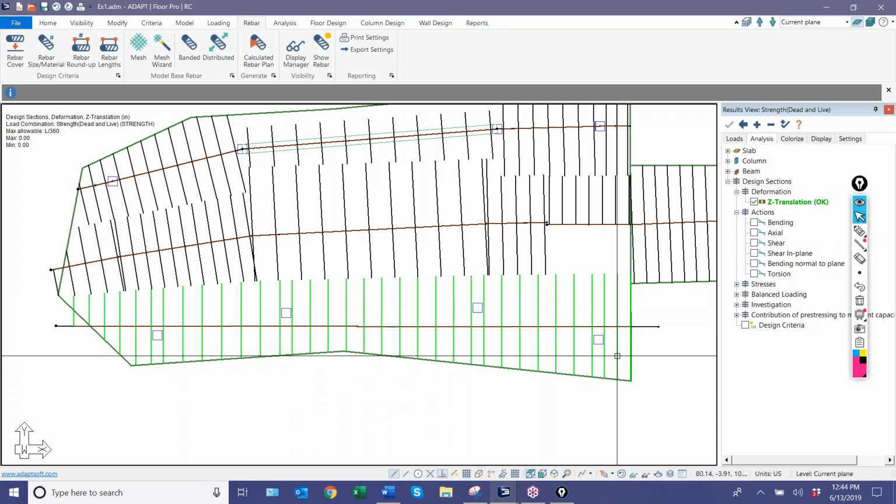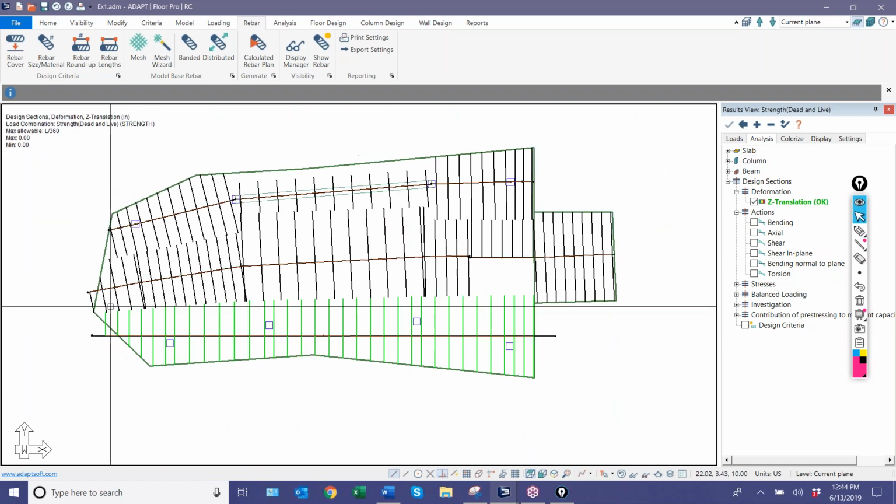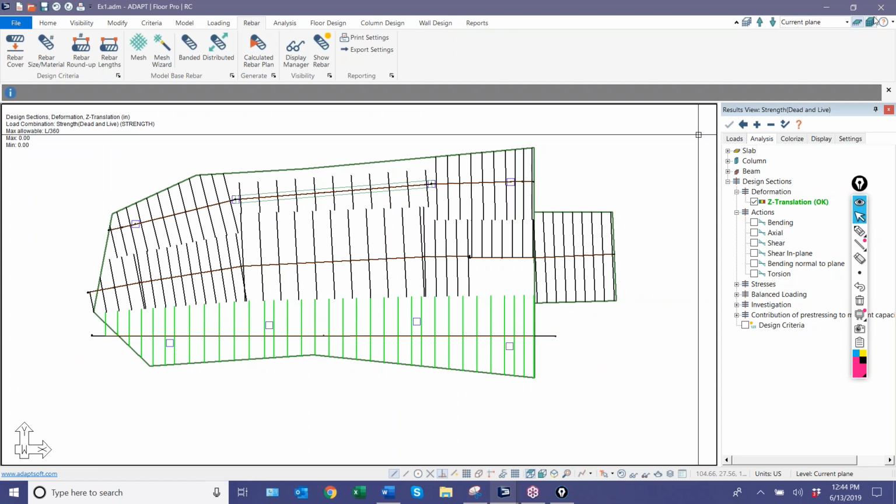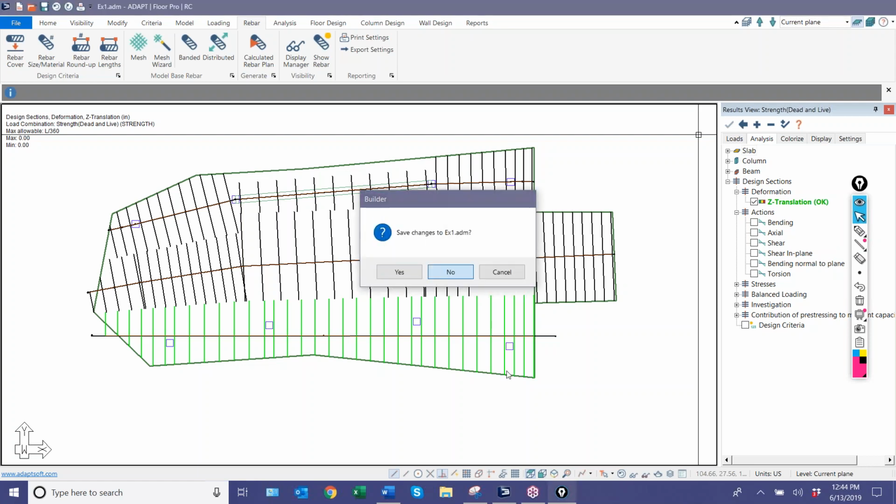So there's a few things that will be proper if you design it this way or if you set it up this way, and there's other things that will not, that would lead you to go back and break this up basically per actual location of a support. So that's important to know. We see models that come through that look like this in the rebar. We get questions on reinforcement or deflection, and this is usually one of the reasons why you see that.